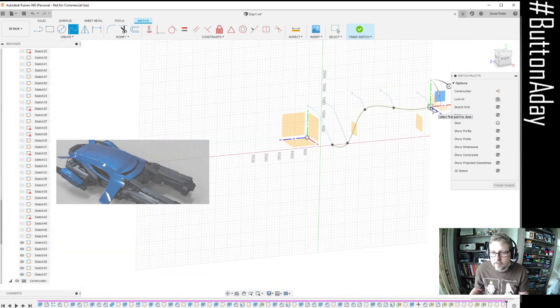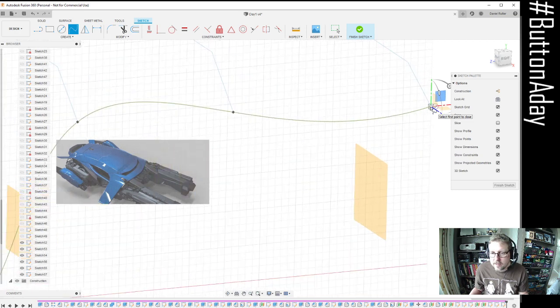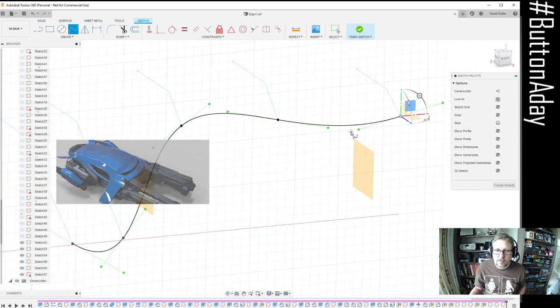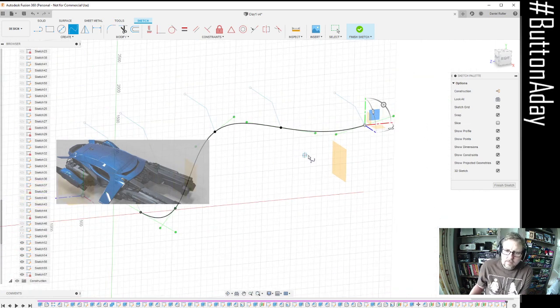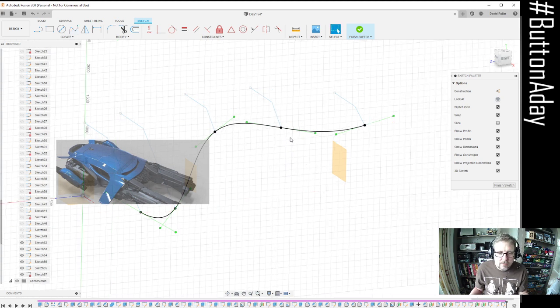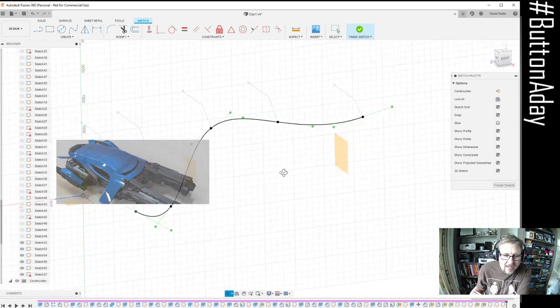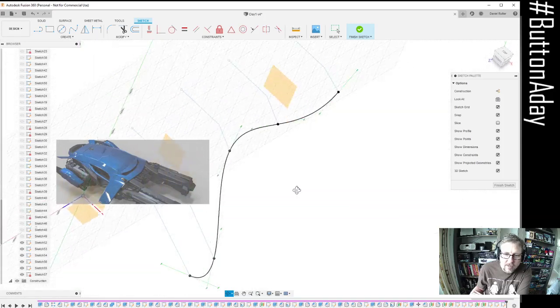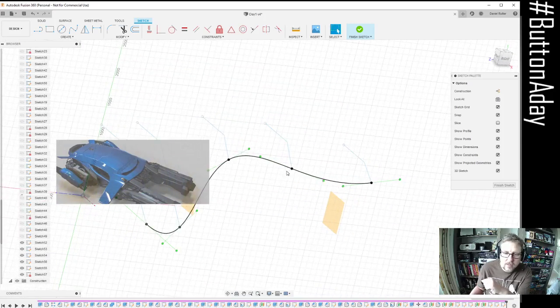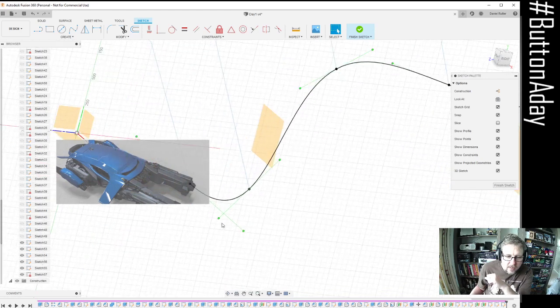Okay. So you see there's a little tick box just here. We can confirm that. Now, splines are brilliant. And you can see I've still got the spline tool floating around by my arrow, so it thinks I want to start drawing another spline. I don't, so I can hit escape, and now I can actually just start selecting things. And if we rotate round, that has indeed worked as it should. We have a 3D sketch that's matching all of those points, and we have these green handles that we can now manipulate.